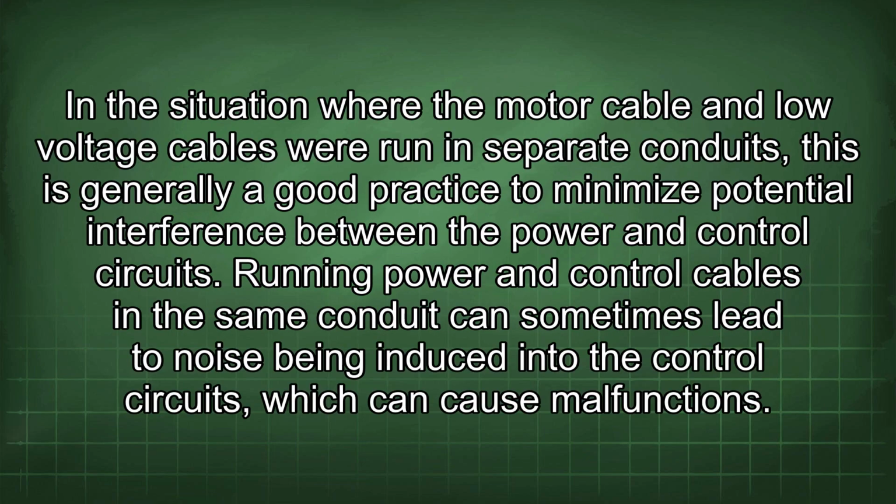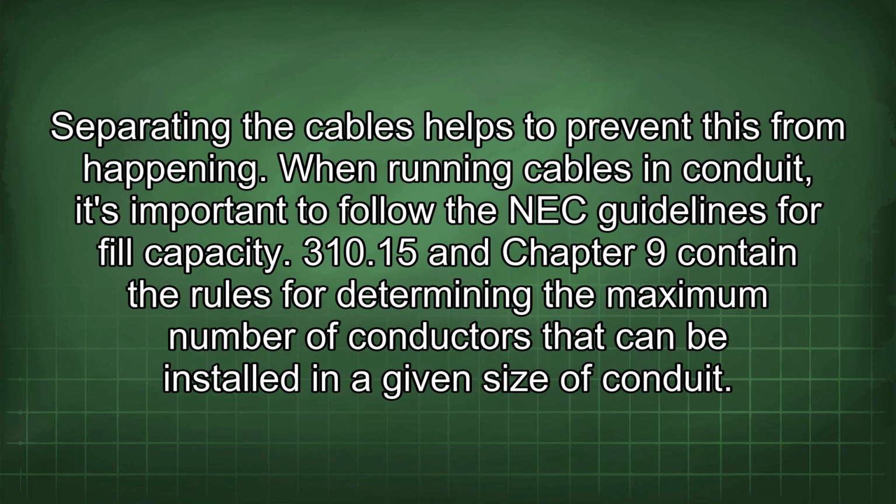In a situation where the motor cable and low-voltage cables were run in separate conduits, this is generally a good practice to minimize potential interference between the power and control circuits. Running power and control cables in the same conduit can sometimes lead to noise being induced into the control circuits, which can cause malfunctions. Separating the cables helps to prevent this from happening. When running cables in conduit, it's important to follow the NEC guidelines for fill capacity.